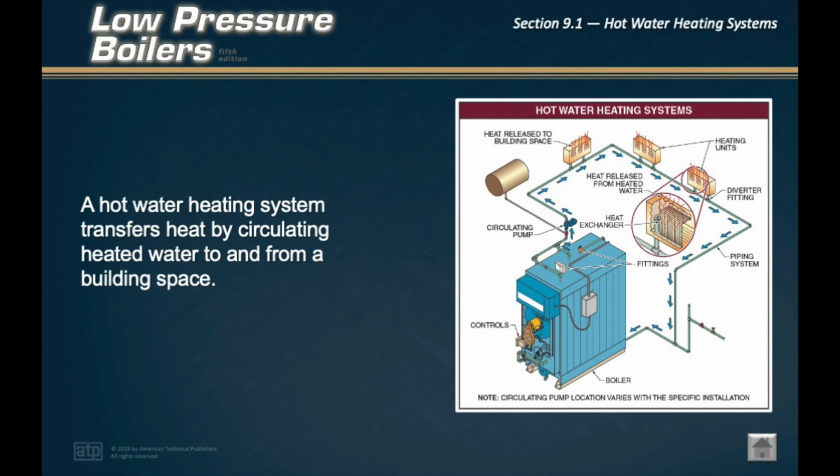A typical hot water heating system will operate around 170 to 180 degrees for the supply water, and about 150 to 160 degrees for the return water. Keep in mind, these numbers will vary considerably. Modern hot water systems will typically use a control scheme that resets the water set point based on changes in the outside air temperature.